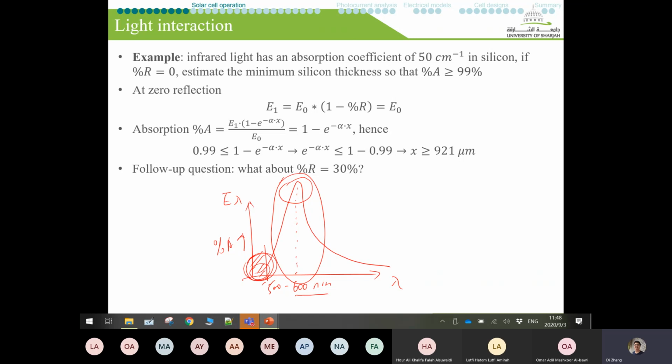Okay, so if you go from the quantum efficiency to the energy efficiency, remember we said that you have to consider also the potential from the solar cell. But then if you lose energy from the blue portion, the problem is that you are going to suffer a little bit of loss in the potential. Okay, in the potential. So in the end, the blue portion, yes, they have a significant solar energy there, but at the same time, it's difficult to utilize them efficiently. Okay, even if you want to, but the